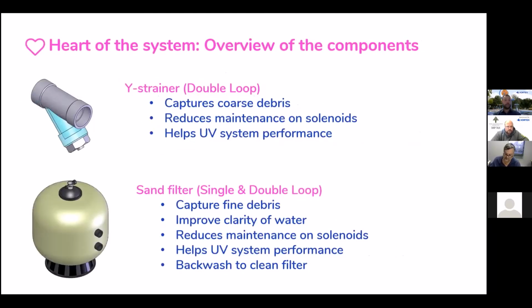Your Y strainer is going to capture any coarse debris that doesn't get caught in your debris trap. This is going to reduce maintenance, especially on solenoid valves that tend to be replaced probably more than anything as far as your overall splash pad solution is concerned. So keeping up with your Y strainers should be an everyday thing. Keeping up, making sure you're emptying your Y strainer baskets, that'll extend the lifespan of your solenoid valves as well.